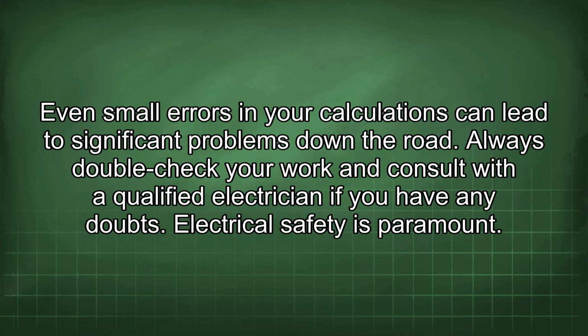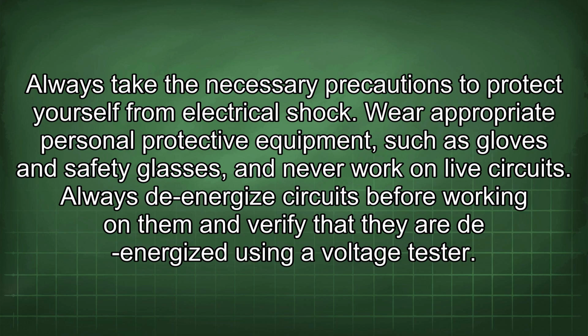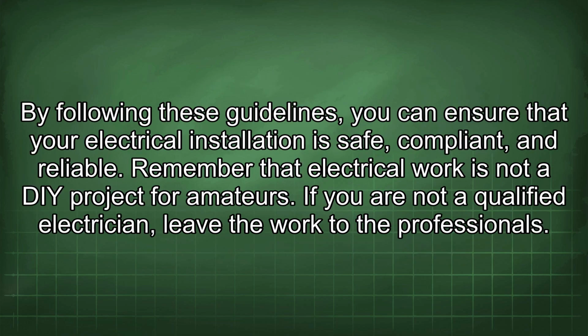Electrical safety is paramount. Always take the necessary precautions to protect yourself from electrical shock. Wear appropriate personal protective equipment, such as gloves and safety glasses, and never work on live circuits. Always de-energize circuits before working on them and verify that they are de-energized using a voltage tester. By following these guidelines, you can ensure that your electrical installation is safe, compliant, and reliable.